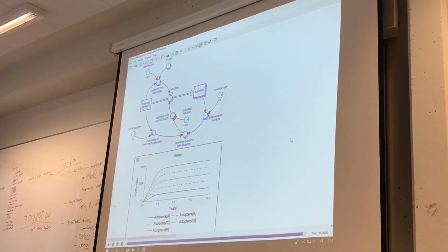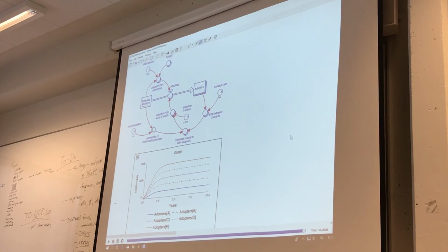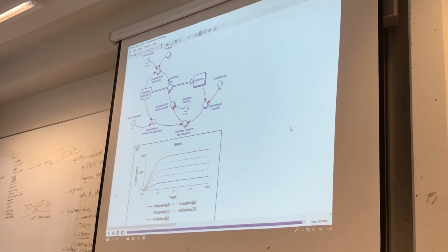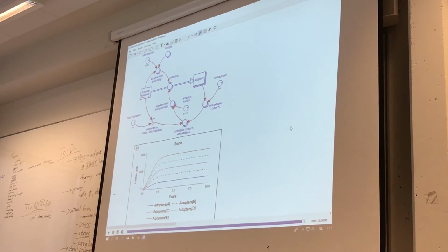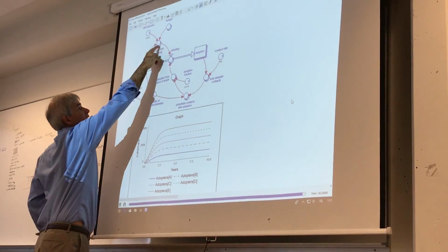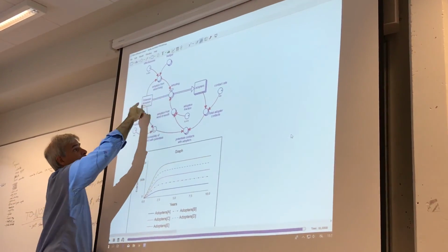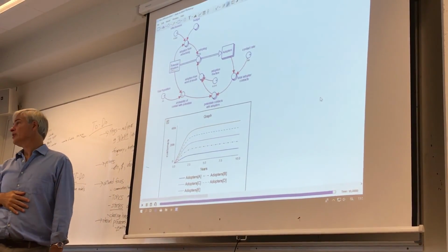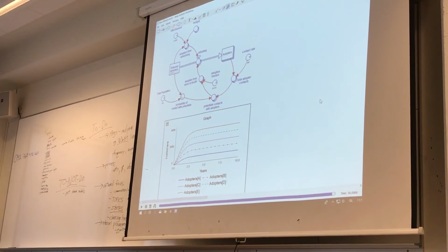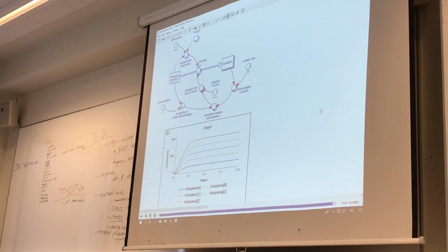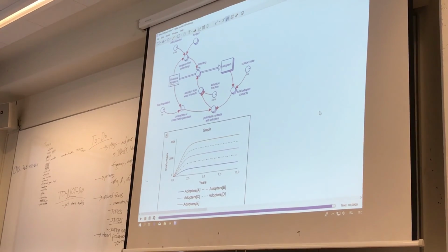So I just showed you how you can put a dimension name into an equation if you need to, which is very quick. Do you need all the variables in a loop to be arrays? Typically, all the variables in a loop will be an array, but it's not a requirement. Here I have a loop, and everything in it is not an array, and I have a loop here, and everything there is not an array either. So you really need to think about what needs to be an array and what doesn't. You can't just say, oh, it's in a loop, so make it an array. That would be great if you could, but you have to think about it a little.